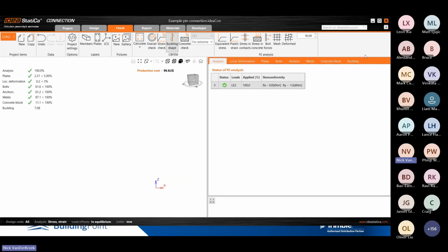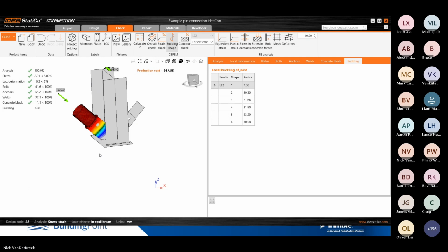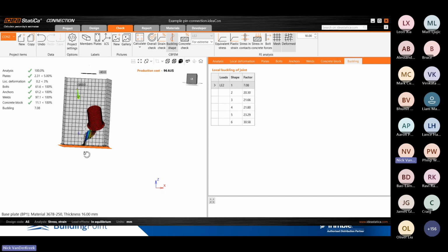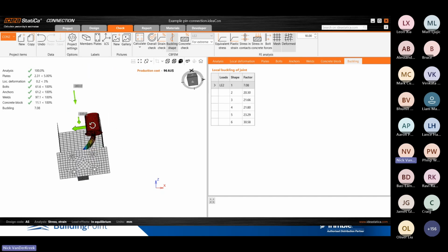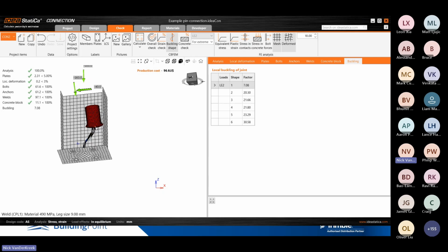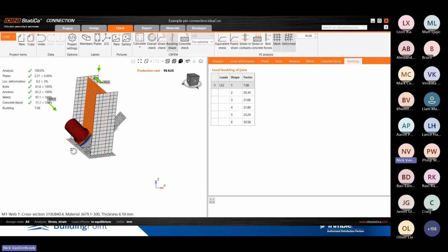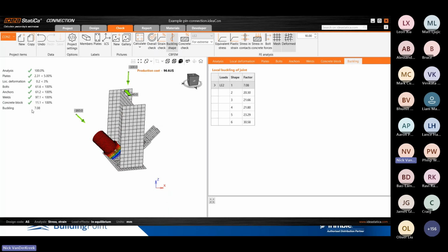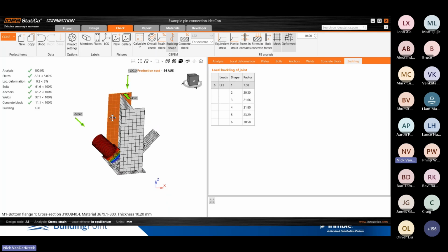and depending on mesh and deformation, we see the sway mode exposed, which is what can happen, of course. Even if the other end is fully welded to a solid support, it would be quite long. In general, it would not be able to prevent sway here if this connection wants to buckle. So, in this case, with sway exposed, I would look for at least 4 as a buckling load factor, and we've got more than that. So I would be satisfied with that result.